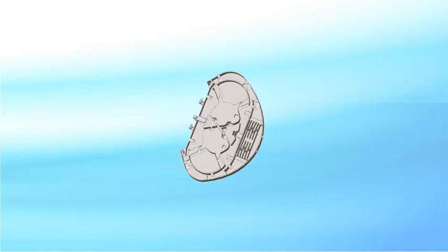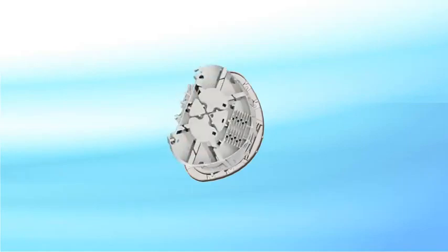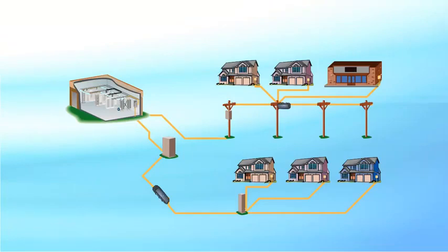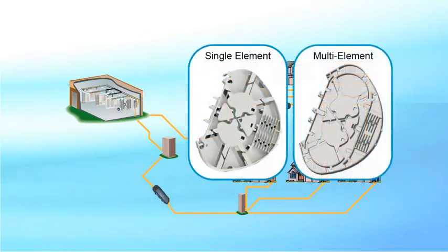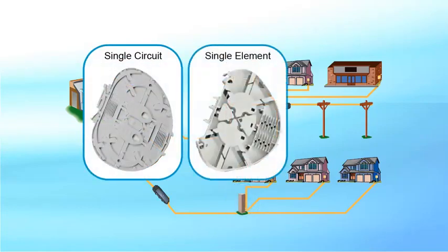A fiber management system should allow modular combination of splice trays with the above-mentioned circuit separation levels. Depending on the application, the type of splice tray can be changed. For example, in a long-distance network where cable segments are spliced together in track joints and where closure re-entry is not expected, the SE and ME splice trays are typically used. In the distribution points of an access network where frequent re-entry is expected over the lifetime of the product, the SC and SE splice trays are usually used.